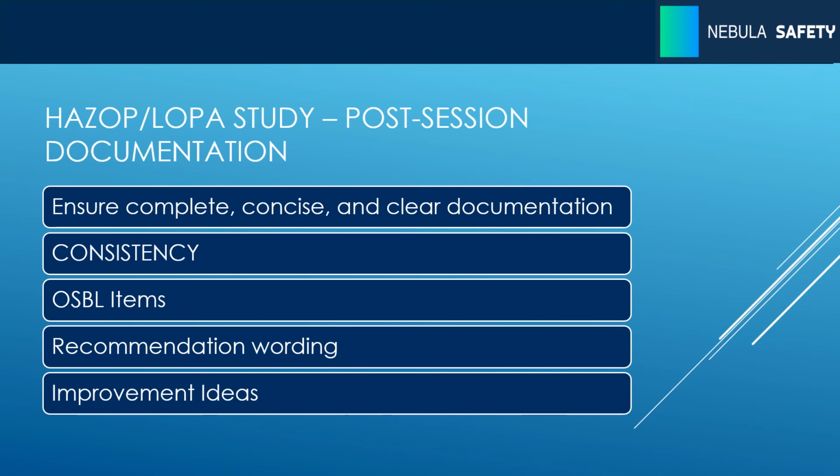So you really want to make sure that those consequences are developed properly so that maybe a different team, or once again, 5 years from now, it is most likely going to be a completely new team who are going to review and revalidate your work, and you'd like to make sure that they can understand the thought process that went into that analysis. It should be clear where the ultimate consequences are: personnel impact, environmental impact, business impact, etc. A scenario should never be left at just overpressure of the vessel. It's incomplete. It doesn't include whether loss of containment has actually occurred.